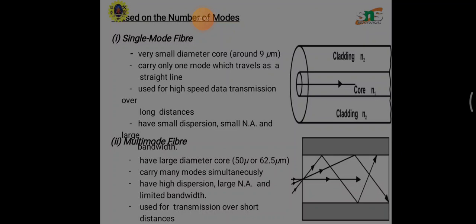And multi-mode. The multi-mode fibers are useful in manufacturing both step index and graded index fiber. The multi-mode fibers are made of multi-component glass compounds such as glass clad glass and silica clad silica, doped silica, etc. Here the core diameter is very large compared to single mode fibers, so that it can allow many modes of propagation through it, and hence they are called multi-mode fibers.